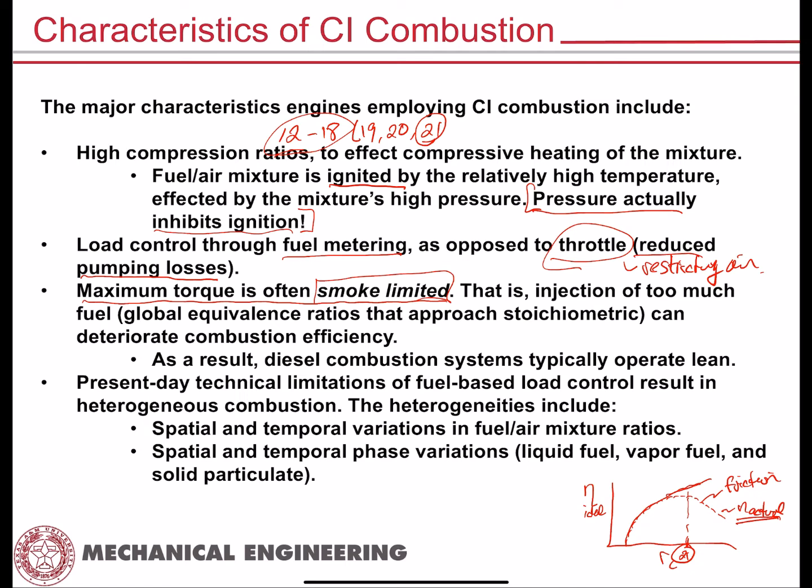Now, what happens is, and we'll go over this more in the next few slides, just spend a moment visualizing with me what actually happens during compression ignition combustion, right? So you induct pure air into your cylinder, and this pure air gets compressed during the compression process. Remember, there's no fuel in the cylinder, there's no fuel in the mixture yet. And the piston approaches top dead center. At that point, fuel is injected into the cylinder, and that fuel then has to go through a long series of physical and chemical processes before ignition actually takes place, right?